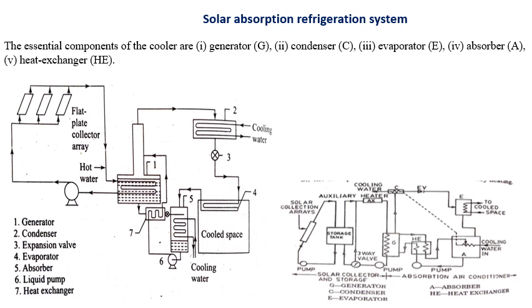So from the point of view of use of conventional energy source, there is a single index of performance for rating cooling process, that is COP. The ratio of the amount of cooling to the energy required is called as COP. Okay. So for solar operation there are two additional factors: the temperature required in the solar collector to drive the process, and the ratio of cooling produced to solar energy incident on the collector.